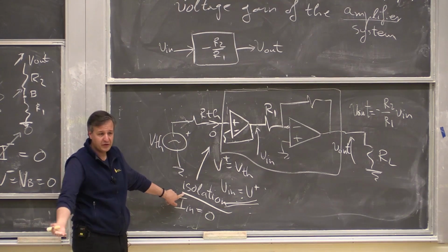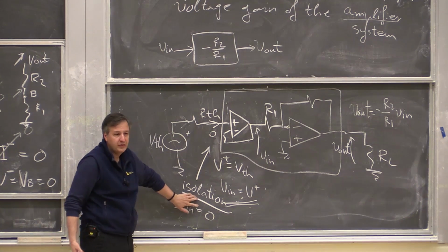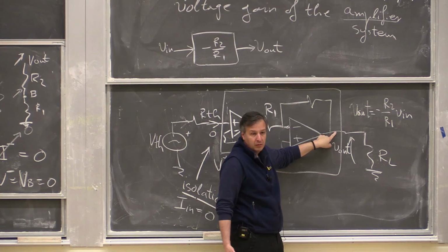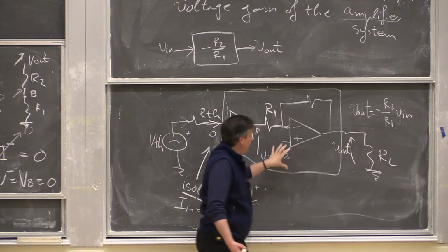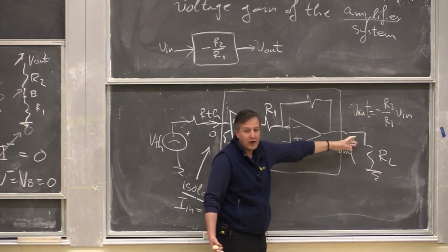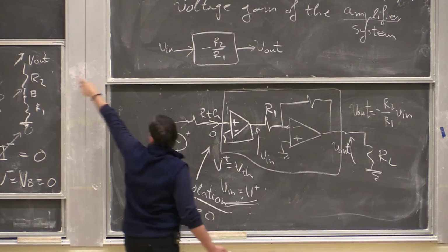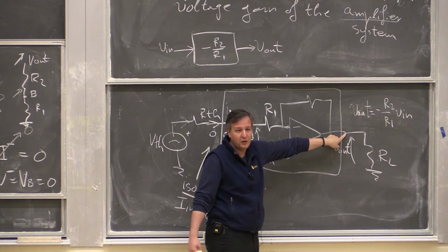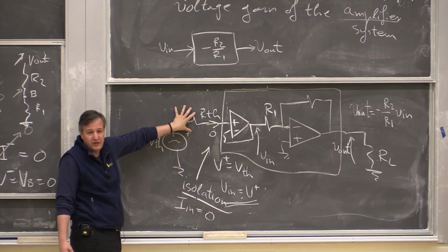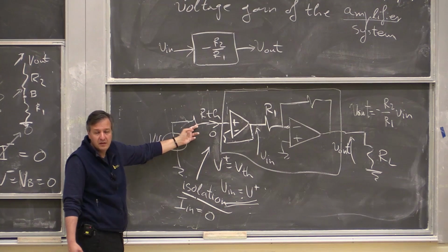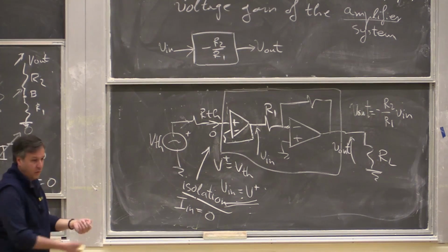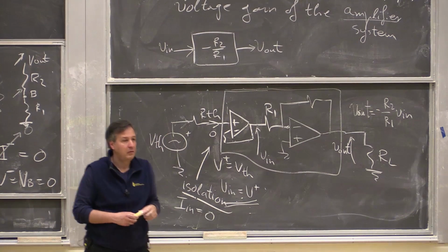So this is one of the key principles. When you start composing bigger circuits, you will want the follow-on circuit to not load the previous circuit. And if you have an output, in this case, if I was composing another block like this, with this op-amp output, I can drive anything. I could drive even this inverting amplifier directly, simply because here I don't care what the load is. I have a voltage source driving the load directly. Here I didn't know what my previous block is. If it had some serious resistance with it, then I need to isolate. If it's just an ideal voltage source, I don't need to isolate, because the voltage source will just keep its voltage across. Okay. Does that make sense?